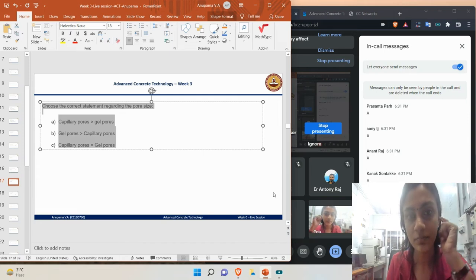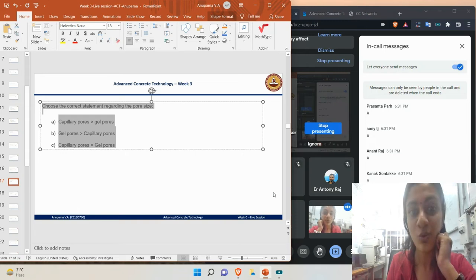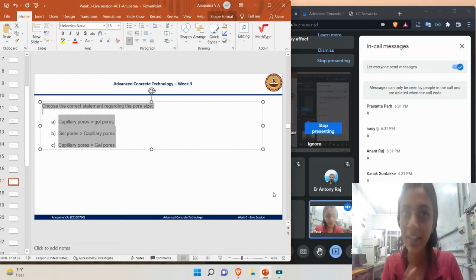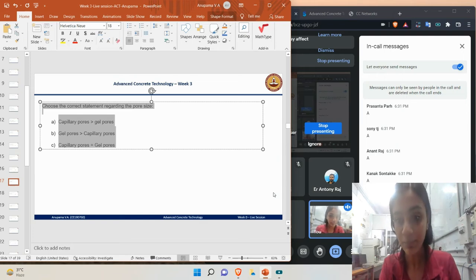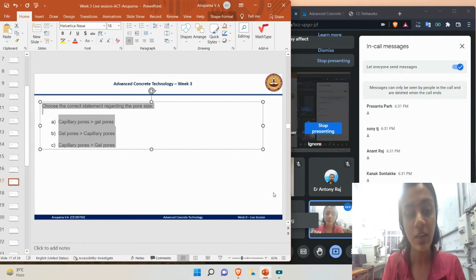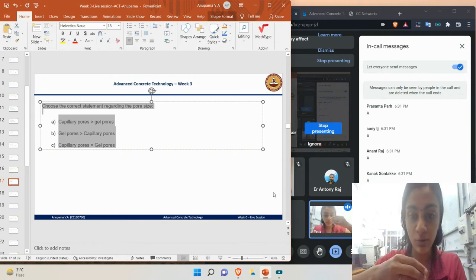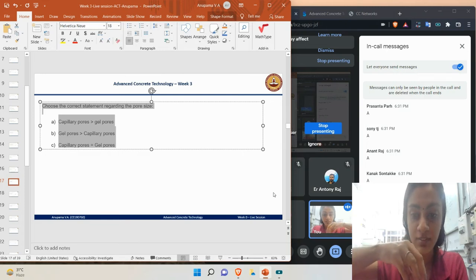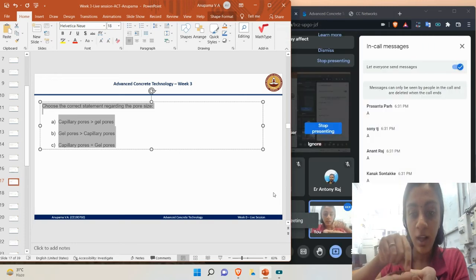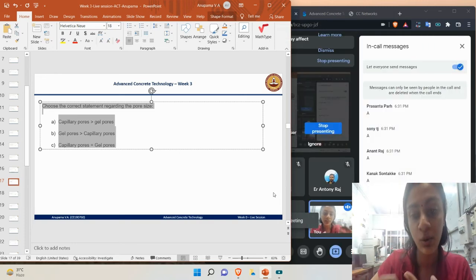So in that case, if the specimen is placed in such a way, can't we see the depth of that pore? No, that is the problem. In scanning electron microscopy, especially backscattered electron imaging, the specimen preparation itself means we make a flat, polished surface. The more polished it is, the better. So the camera is facing the top surface. If I am looking at a flat surface, I'm just seeing a hole. I clearly don't know how deep the hole is.